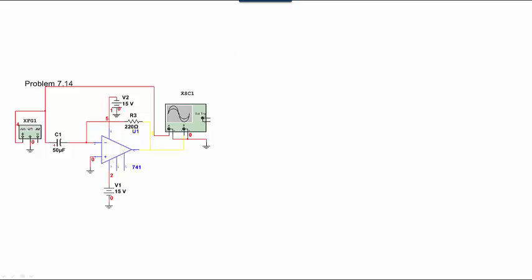Okay, so for this circuit, we have a V here, and we can have a C dV/dt, and then it would be equal to, current in equals current out. So if I do that for this circuit, it's C dV/dt equals, watching my signs now, I'm going this way, so it's minus V out over the feedback resistor.